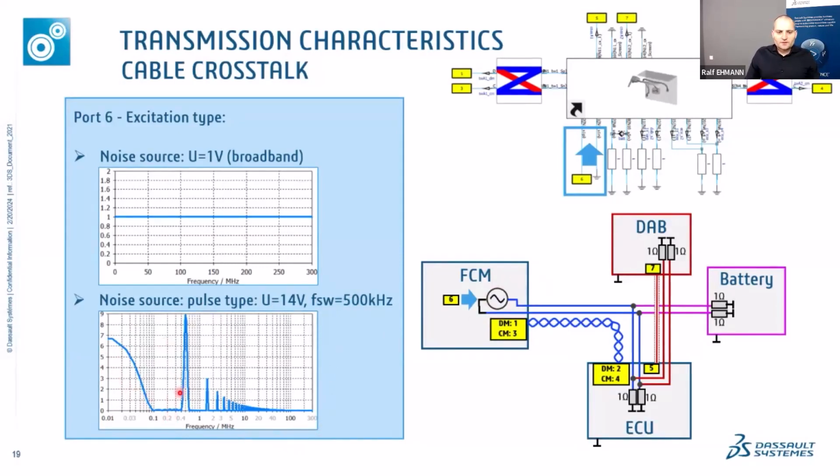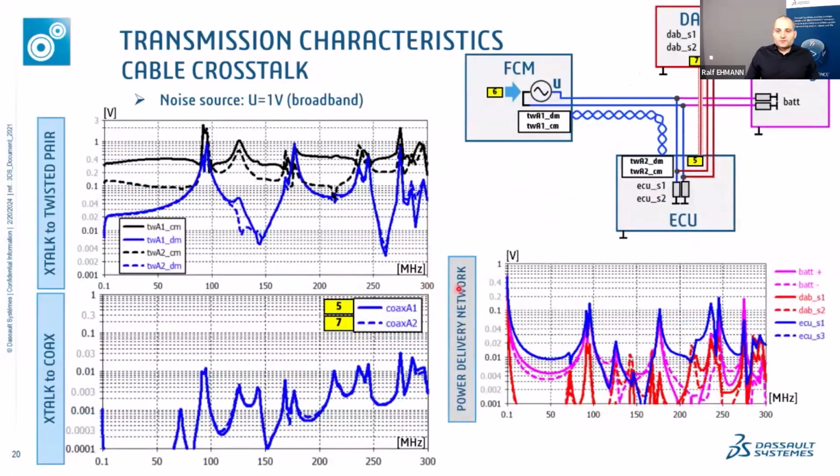So you can also specify directly from the Design Studio a simplified version of the switching noise. You can also use a macro for that, which can be found in the EMC workflow button. And there is also the possibility to directly import this spectrum as an ASCII file if there is a typical device running. And there is also the possibility to attach the exact circuit in the Design Studio of that given circuitry, generate the signal by circuit simulation, and then feed it here. I used the absolute worst case scenario for these results, just for information and explanation.